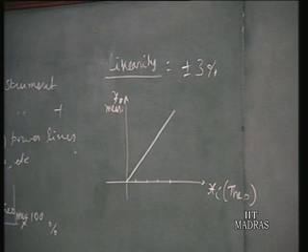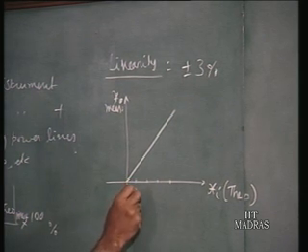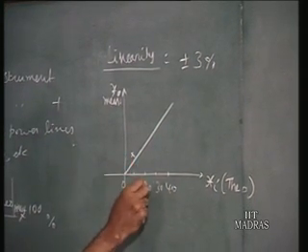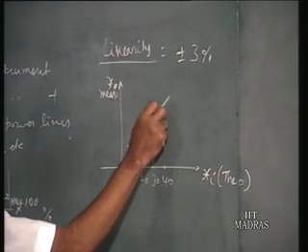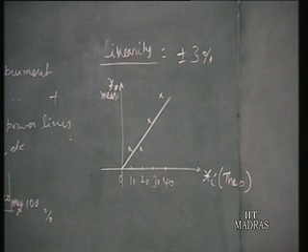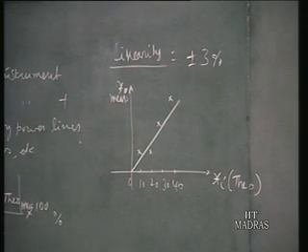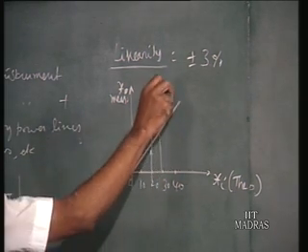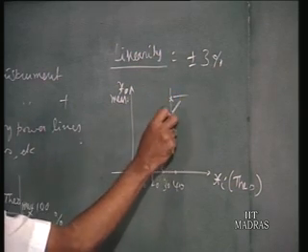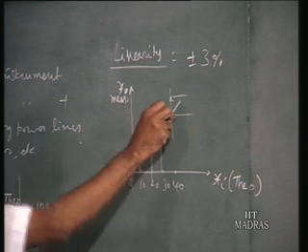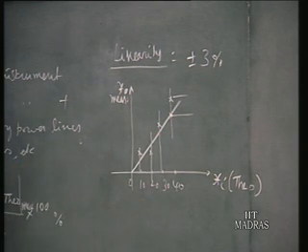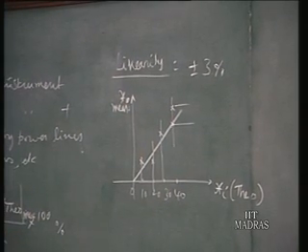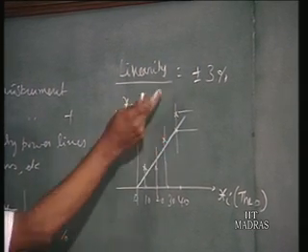And when we have this, say it may be 0 bar, 10 bar, 20 bar, 30 bar, 40 bar. When 10 bar, then the reading lies somewhere here, 20 bar reading lies here, 30 bar reading lies there, and 40 bar may be lying there. Suppose readings of the instrument under study vary like that, then you will find the maximum deviation for the different inputs. And here you find the last reading has the maximum deviation from the theoretical value. This is supposed to indicate this point, but instead of 40 it shows say 45, something like that. So the points are lying not on the linear line, that is, the line means the linear characteristics of the instrument, they are away from the linear characteristics.